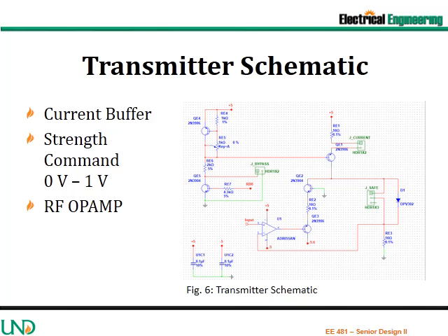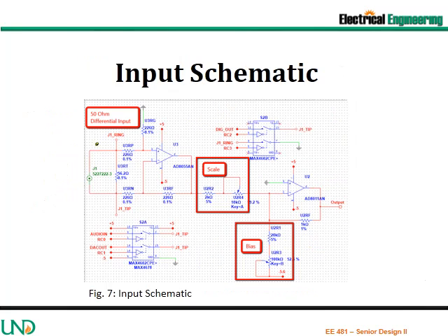The current source is enabled by having the current jumper installed as well as having the microcontroller turn on transistor QE5. A 300 MHz op-amp is currently being utilized to force compliance of the laser diode to the command signal. A strength command is desired to allow compatibility with different components. 1 volt is full scale, 0 volts is only the bias current. Differential input reduces common mode interference.